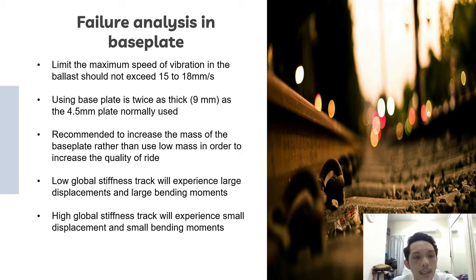Alright, so let's speak about the stiffness of the railway track. Stiffness is really hard to understand because it is a non-linear subject. A track with low global stiffness will experience large displacement and large bending moments, while a high stiffness track will experience small displacement and small bending moments.